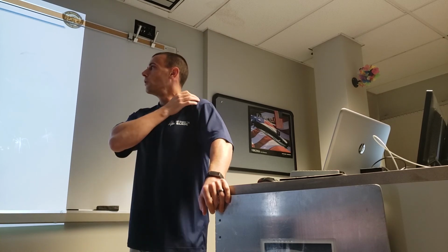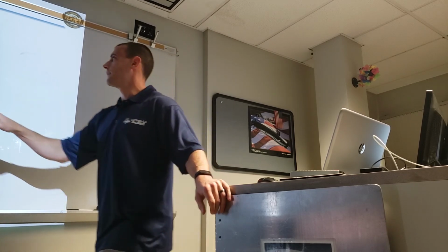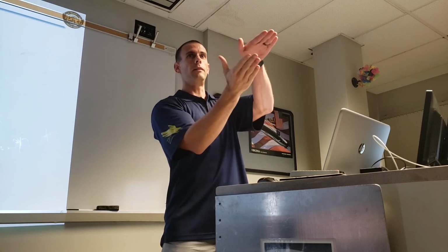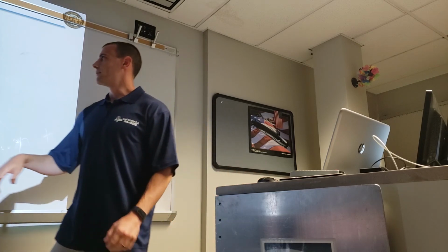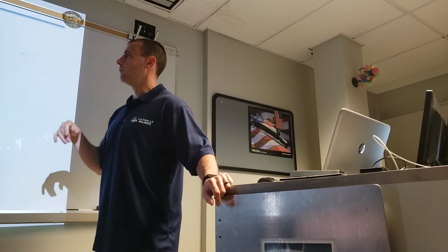And it does matter where the shear center is and the neutral axis is, right? So you just put that stuff in, and then you have to tell it its orientation, right? So if you did have an I-beam, if you have a sketch, it doesn't know how to orient that I-beam. So you give it a vector and whatnot. I mean, it can be hard to keep track of, but that's part of the process, is define the geometry, whether you're doing it in the FEA or it's been done in the CAD for you.